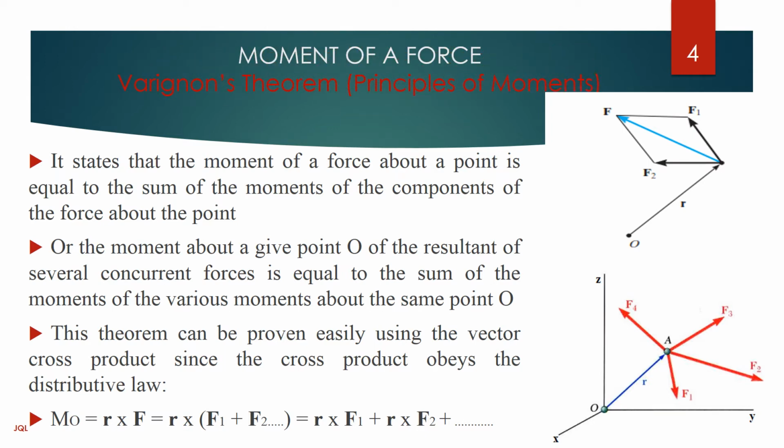Now, the principle of moments. It states that the moment of a force about a point is equal to the sum of the moments of the components of that particular force about that point. The moment about a given point O of a resultant of several concurrent forces is equal to the sum of the moments of the various forces about the same point.